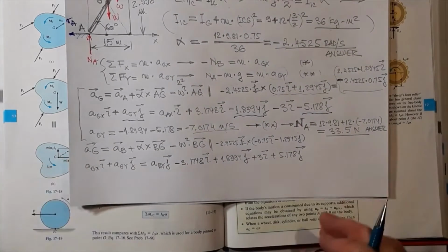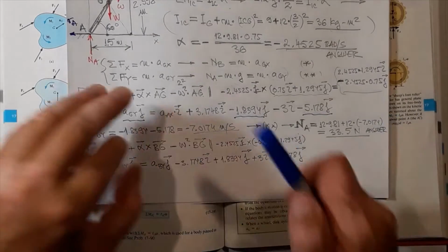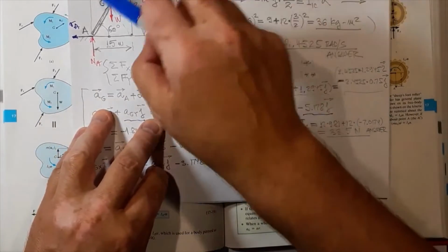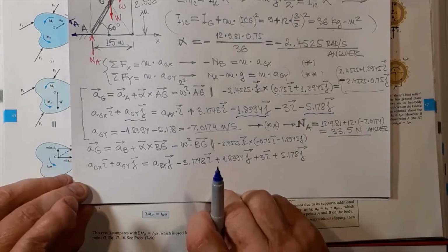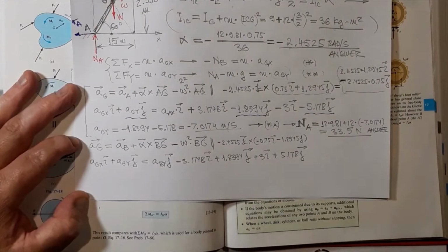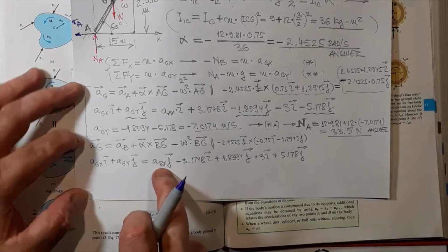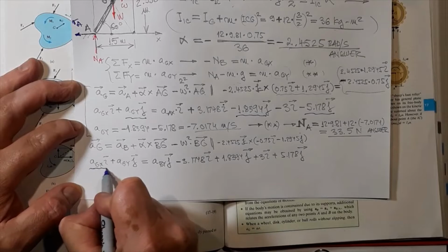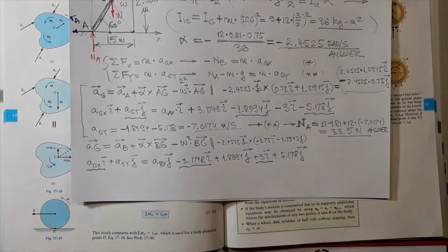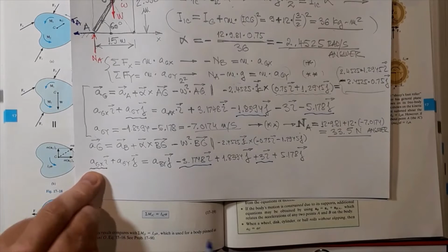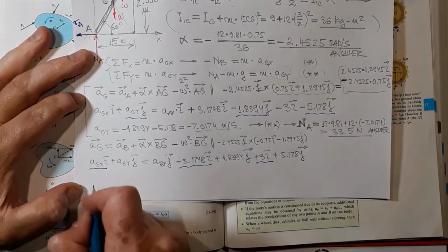A useful equation here, although you could start with either relative motion about B or relative motion about A. The useful equation this time is the one along the i-axis, because the point B has no acceleration along that axis. So I'm going to collect this term with this term and with this term. It allows me to calculate the unknown acceleration of G with respect to x.